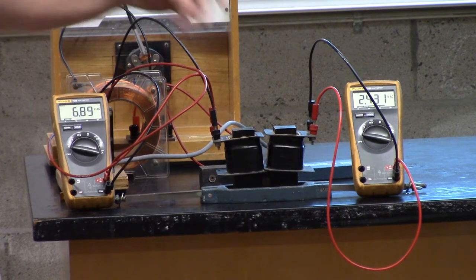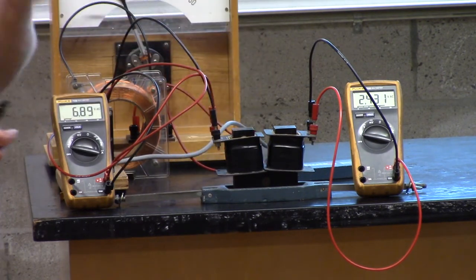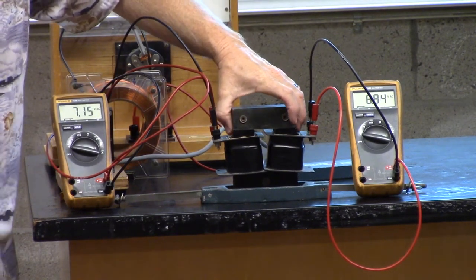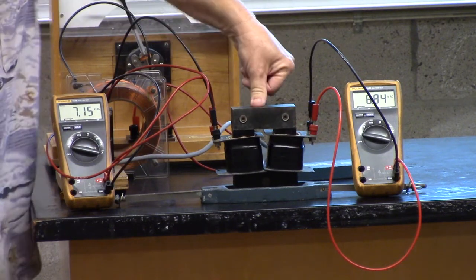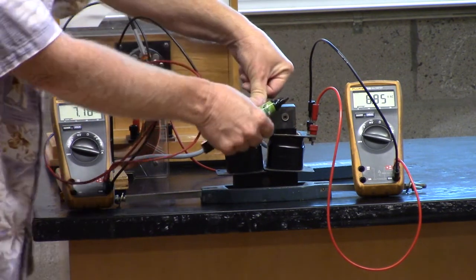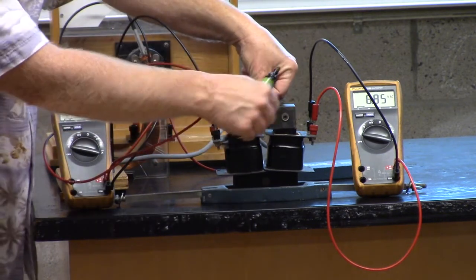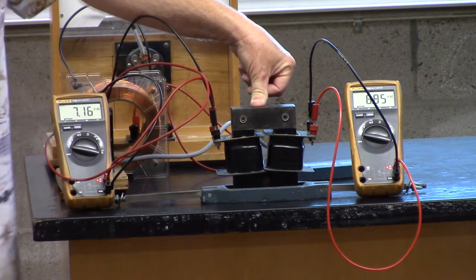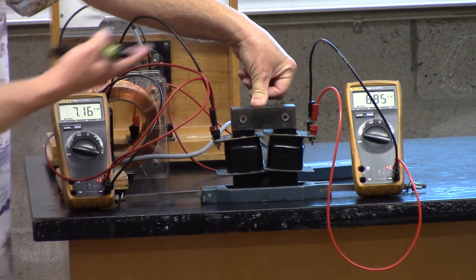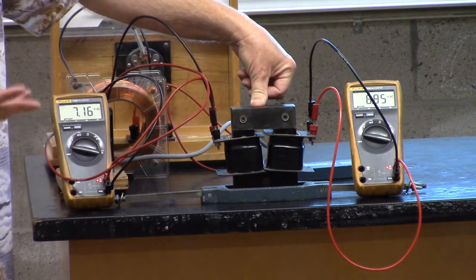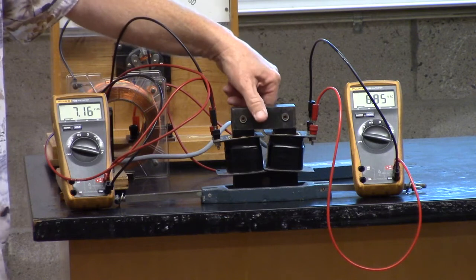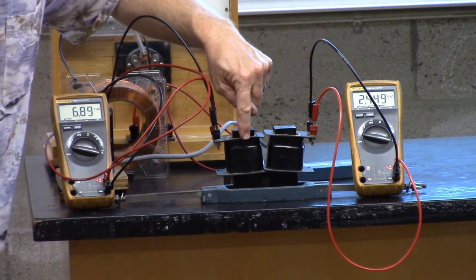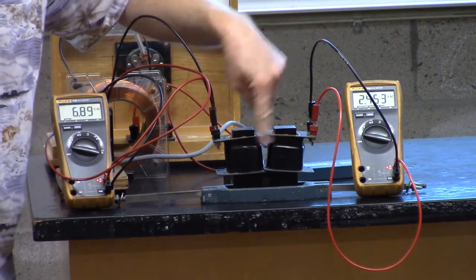Now, it's not really the same amount of flux because I moved this metal bar. So to make it a little better, let me put this metal bar back on here. Let me kind of hold it tight so maybe I can get as much flux through there. And so I'm putting in 7, and what's coming out is 7. Actually, it's a little over 7 and a little under 7. So apparently I'm not getting all the flux, but what I did do is I put 110 turns here and 110 here. So these have the same number of turns.